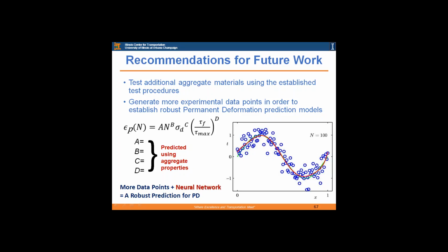One material that's very weak, a high fines limestone, let's say, versus some granite material in NCDOT, a really good high quality material with little fines. The ratio can come up the same in both materials, but their strengths are so different, so the amount of stress they can handle within the unbound granular layer of a pavement system can be quite different for the same ratio.